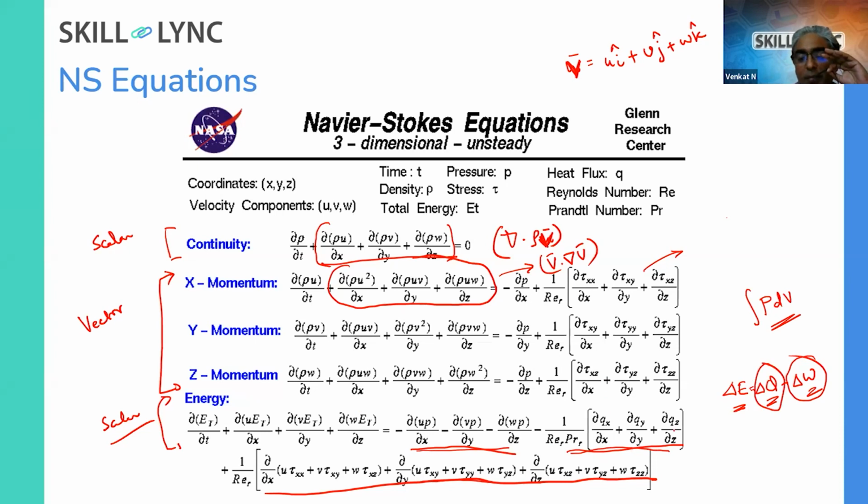Okay, heat diffusion. And there might be some more things, for example, if you have some reacting flow, so some heat is liberated, some Q dot heat is generated by reactions. For example, if you are burning something, a rocket combustion chamber, so we'll have extra terms in the energy equation. Okay, and because of these extra terms, energy ultimately, at least in the gaseous cases, will be shown as temperature, right? So this is the full 3D unsteady Navier-Stokes equations. Okay.